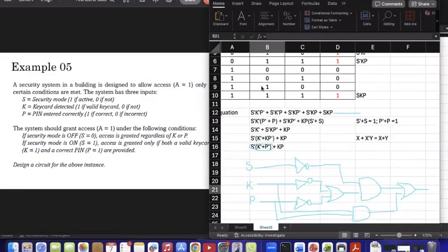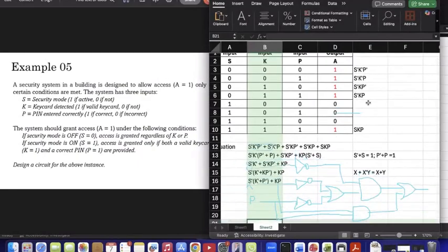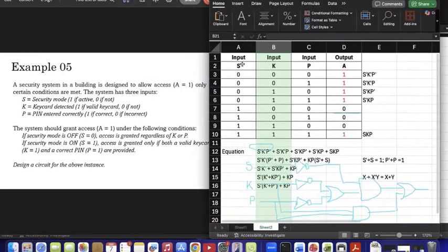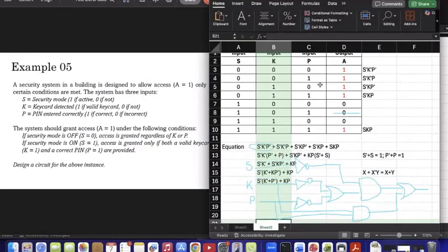So see, you can just find and you get the product of sums or the sum of products, but it is good practice to go with this. Because just by looking at S0, people try to put S bar. But if you are doing the other one, product of sums, you have to do the other way, but it is also quite fine. But people have a practice of using this. Unless specified to put it in SOP or POS, you can go with any method. Is that clear?